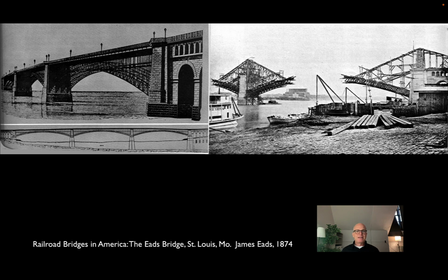He's taken Telford's idea of connecting the arch and the deck, and now here he's using both wrought and cast iron, probably more wrought than cast iron, to build the arch at the bottom. That's actually a beam arch. It's a very shallow arch and therefore subject to a little bit of bending. The deck is fixed to it with these struts that mean that the two work together.